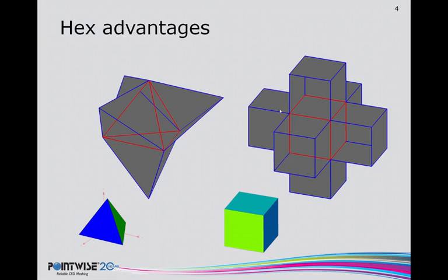Another thing that I should point out is while both of these shapes are inherently 3-dimensional, the neighbors surrounding a hexahedral cell must lie in 3 dimensions if it's a properly formed hex cell. However, for a tetrahedral cell, there are configurations where each of the 4 neighbors can actually lie all within the same plane. And so even though it's a 3-dimensional cell, you're really limited in the amount of information you have on gradients in that 3rd dimension, should those points lie in a certain configuration.